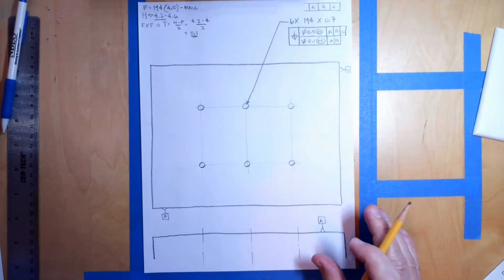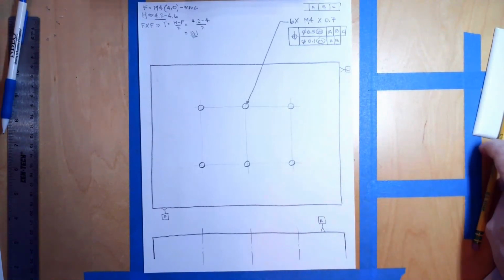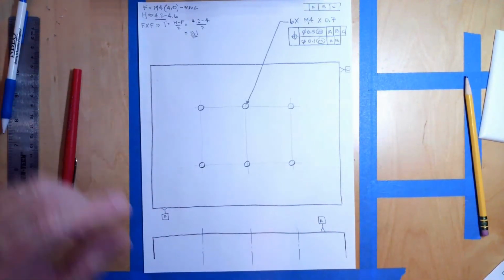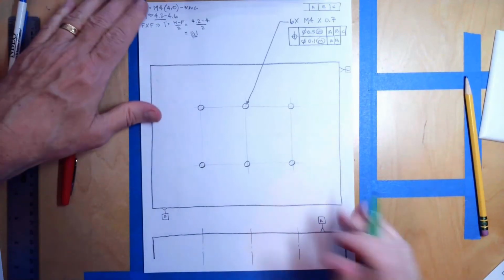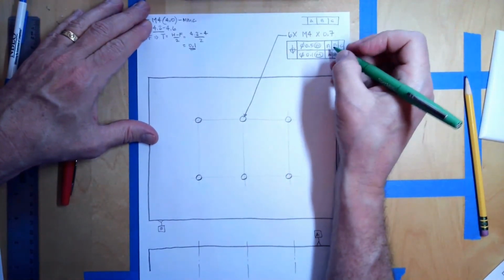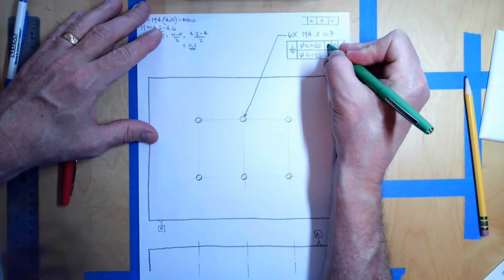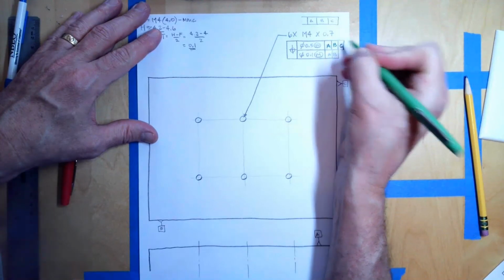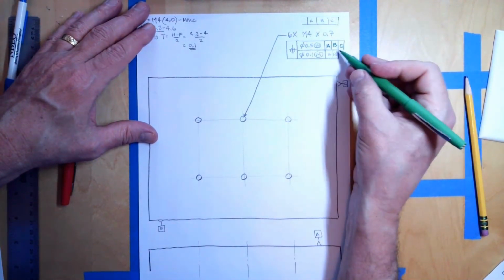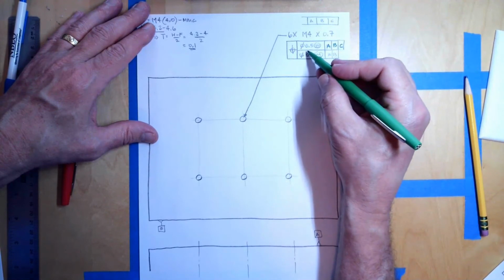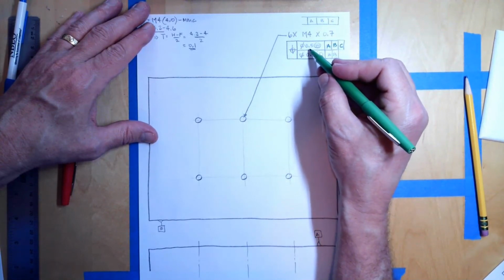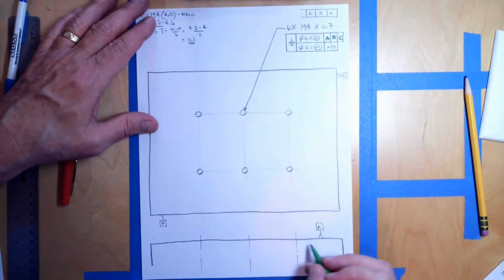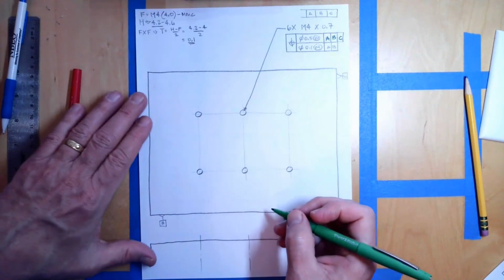Now I'm going to use different color pens here so that it's a little bit more clear. So I'll use green and I'll use red for the different ones. Just so you can get these tied in, the green is going to be the pattern locating tolerance zone, and the datums locating the pattern locating tolerance zone framework is going to be A, 90 degrees, that's understood.